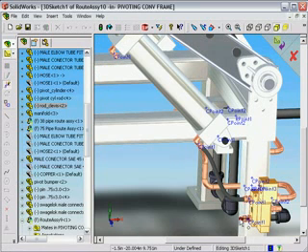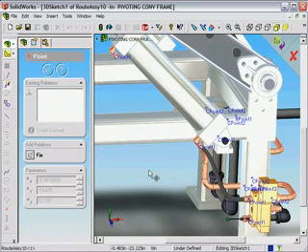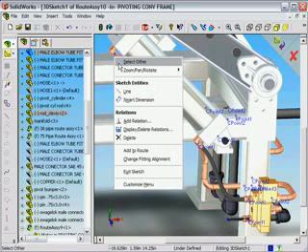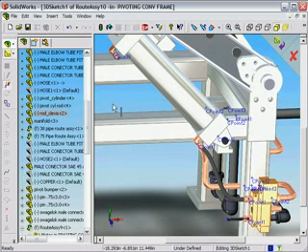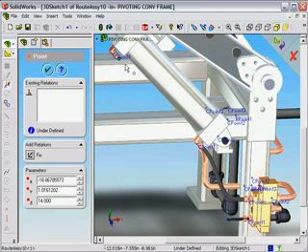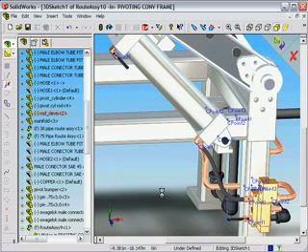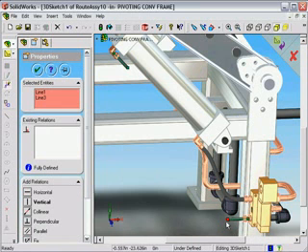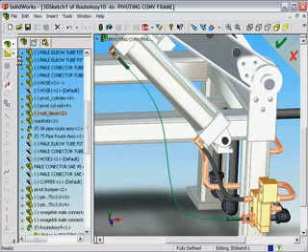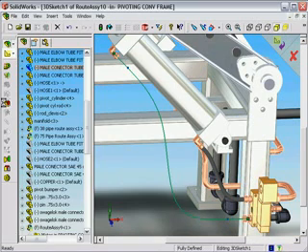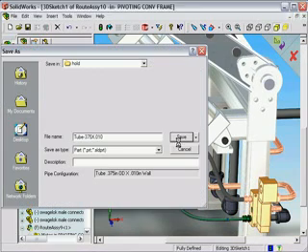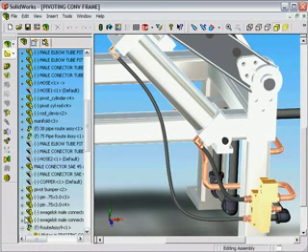Now, just as before, SolidWorks starts the route in the 3D sketcher. In this case, we're just going to drag out the lines, not worry about dimensions from the start and end point of the route. Now, using the fit spline in SolidWorks, we can auto-route the rest of the design for our flexible tube. This saves users an immense amount of time when laying tubes out and gives them a best fit solution for their design. And very quickly and easily, we've generated that flexible hose for use in our assembly.